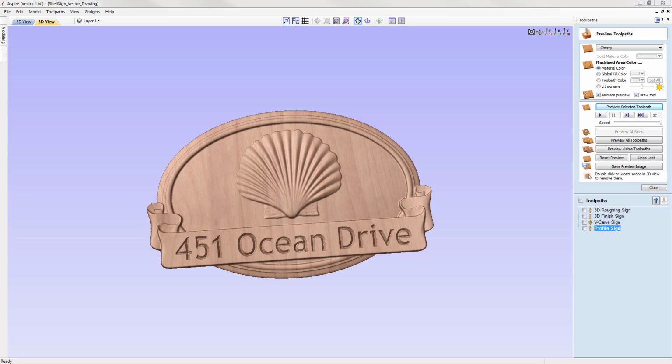And so it's very important that your part looks correct at this stage, as the toolpath preview shows you an accurate representation of what we would see on our CNC machine if we were to go ahead and run these toolpaths. So if something doesn't look as you wanted it here at this stage, you can go back and make edits to the toolpaths, recalculate them until you are satisfied with the results that you can see here in the toolpath preview. And that's what makes the toolpath preview such a powerful tool.